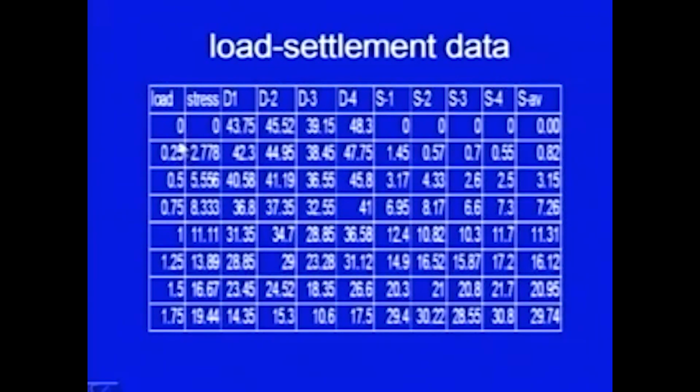And then we applied a small incremental load, and then we monitored this data. Those data are not shown here. In fact, in the field we take data at different times, as I told you, at 1 minute, then 2.25 and so on. So, here only the final readings are shown when the settlements were complete and the system had stabilized. These are the final values for the next incremental loading.